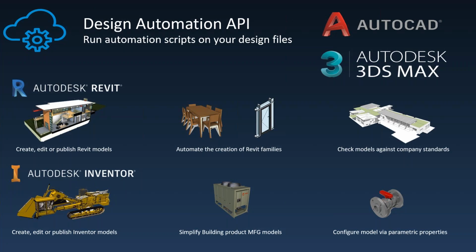Well, there will be 2D views, obviously, for the design itself, but not really any specified sheets. So what we can do is use webhooks to understand, oh, there's a new version here. That new version kicks in and opens Revit in the cloud, and according to a set of rules, it's going to generate the sheets automatically. And that's going to be my new version in BIM 360.